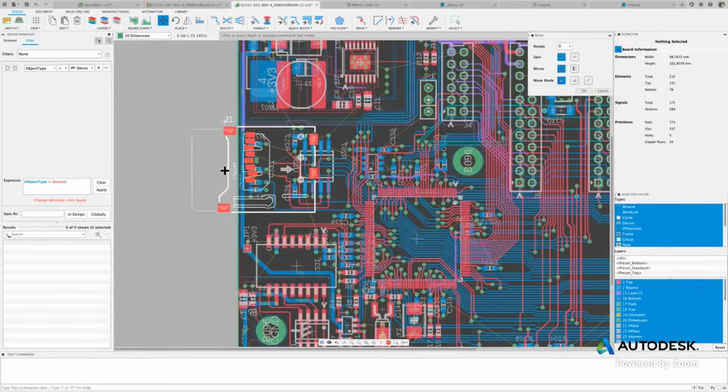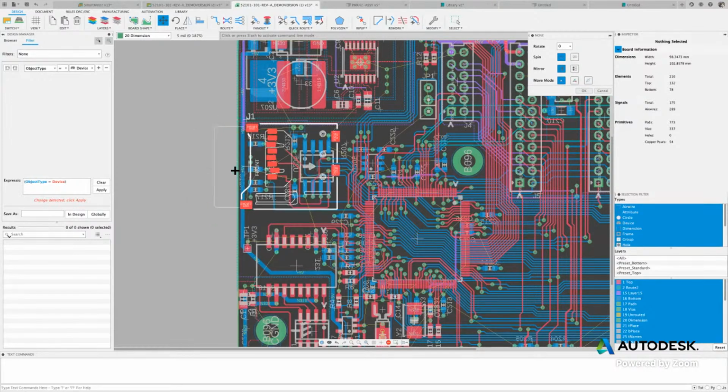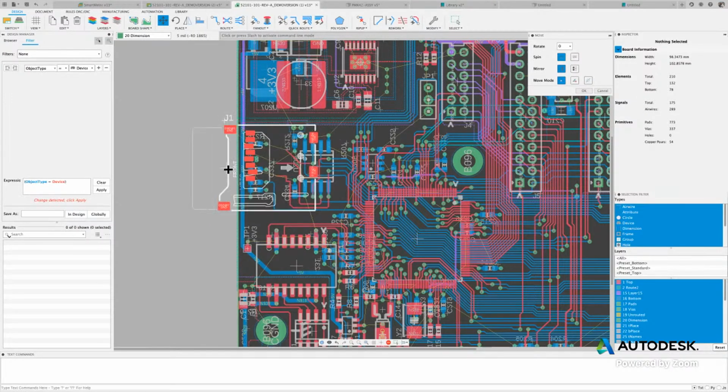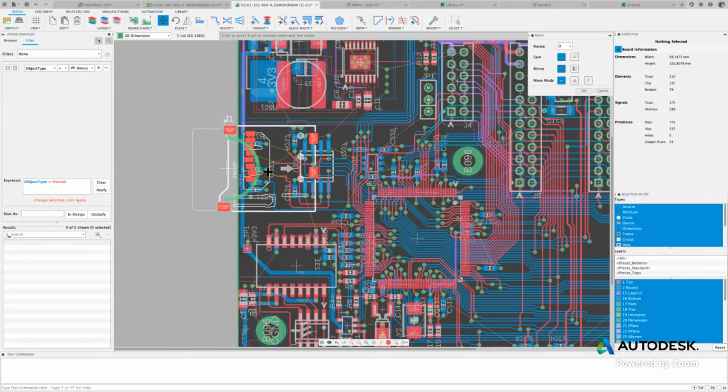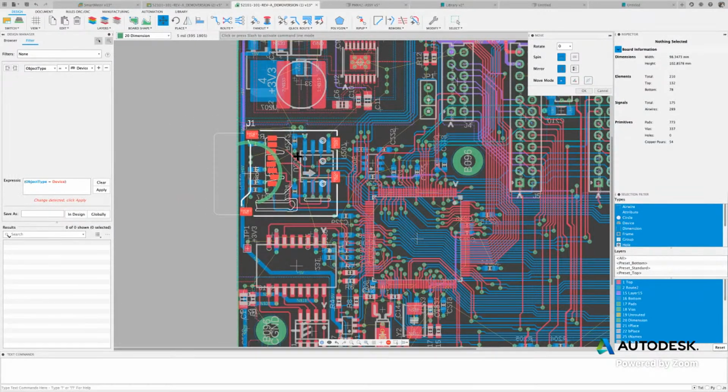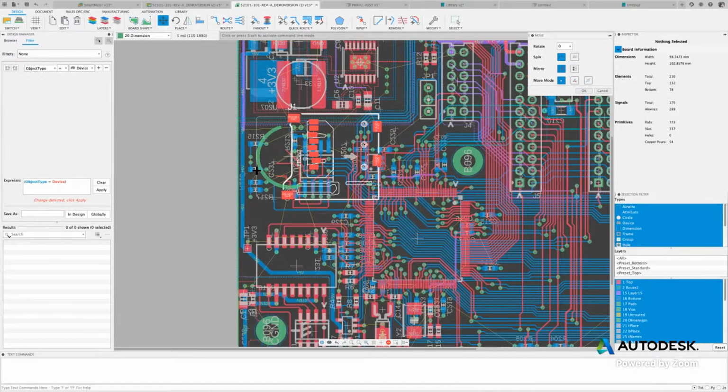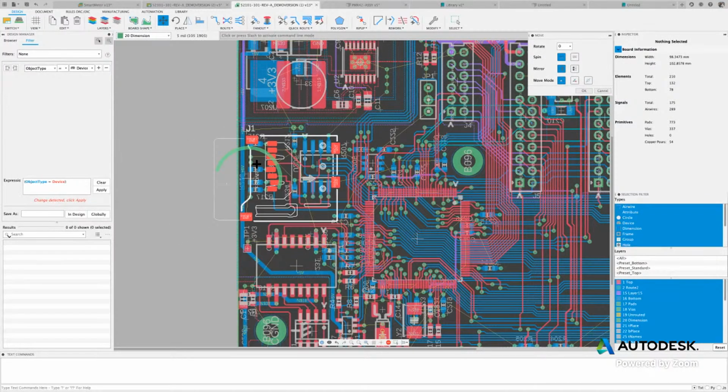I want you to see what happens. As I move it around, it's kind of seeing some violations. You notice that it jumps the board outline. It actually jumps that way. It keeps at least an 8 mil distance from it. It kind of jumps around, doesn't really let me have control of it because it's making sure that I'm not violating DRC at any point in time.